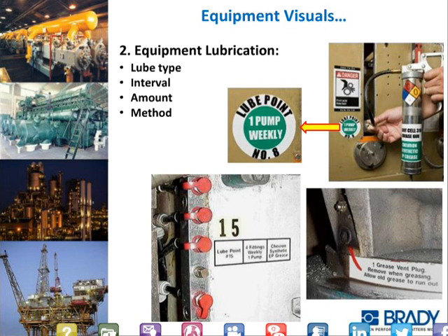So the label merely says, grease vent plug. And it talks about removing it while you're greasing it. Allow the old grease to run out. It finishes purging, and then you put the plug back in and clean up the mess. But it goes back to the principle that bearings like this need more air than grease to run properly. And machines typically don't eat grease. It's got to go someplace. So that's the purpose of the vent plug. So we found those custom labels to be very helpful. And these are make-on-your-site kinds of labels.